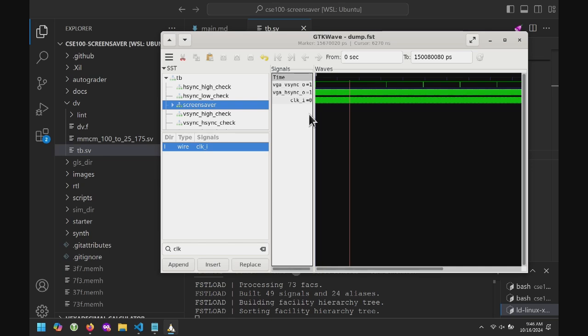It's a very common hobby project of people trying to get into FPGAs for the first time, or getting into chip development. Because unfortunately, you can't really do this using a microcontroller project, just because you can't have code that runs fast enough on a microcontroller to actually implement VGA. On a microcontroller, you're bounded by, I don't know, maybe 1 megahertz. You can't do it at a precision of 25 megahertz. So this is one of the best ways to utilize FPGAs in a hobby project or in your own projects. If you look online at what other people have done with FPGAs, one of the biggest things is implementing VGA and doing something cool.